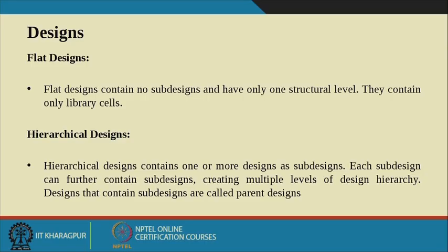Then I have talked about design methodology. What are those design methodologies? One is flat design, another is hierarchical design. What is flat design? The flat design contains no sub design. It has only one structural level, that means there are no sub blocks. Only one module contains the whole description. In that particular HDL file, it contains the whole description of the circuit. That is flattening of the design.